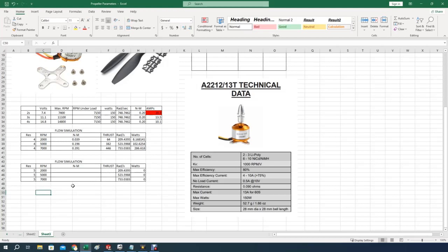In fact, I'm going to change here. I'm going to write the word. Our target is to hit eventually 150 watt. I will say plus minus 10 watts. Like, for example, it could be between 140 minimum to 160 maximum, and you will be okay. Whatever RPM you come up with would be within that range. So as the lowest range, 140, as the highest, 160. So that's where you are for the target of the watts. Not like in this case where I was targeting more the torque, but I'm now more aware that the best way to do this is by targeting the watts on this motor, and that will do.